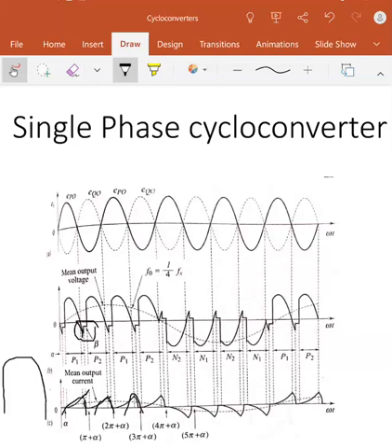It should be following the same waveform? No, it is not going to follow the same waveform, because we are having an inductive load, and the inductor will not allow the current to increase like this. It will make the current increase in an exponential manner, and after that the current decreases, increases and decreases in the exponential manner only. Or you can say in some delayed manner. In this way we are going to get the output.